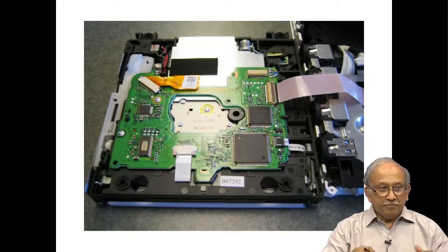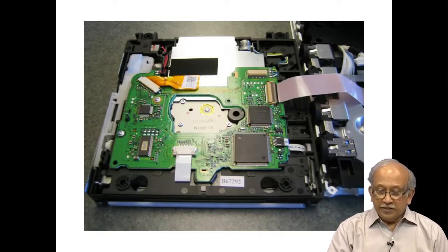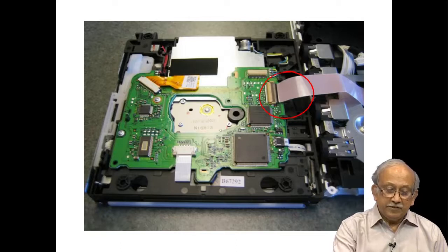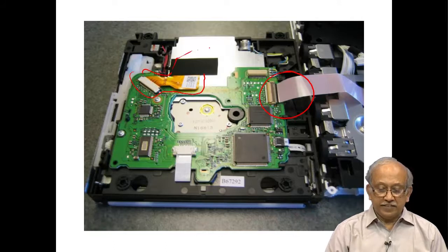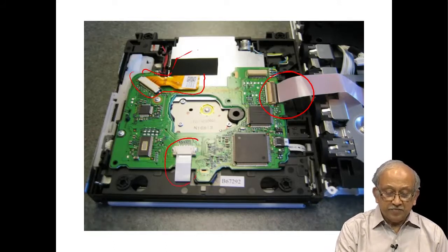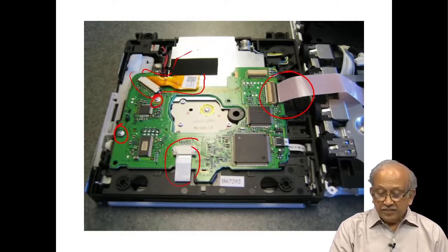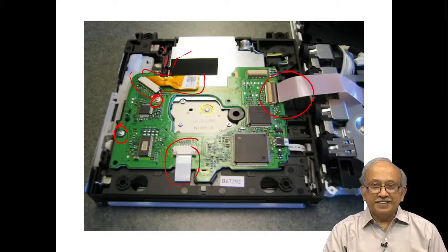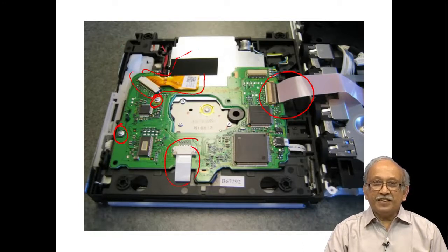That is, you make sure that things fit naturally in all the places. See, in one edge here they have made the connector, and here it is at an angle like this, because the connector is folded and taken off somewhere. And then most important, you have the fastening screws you see here. Two or three things you will notice: fasteners need not be located at the four corners, and very rarely in a professional equipment is the printed wiring board a rectangular thing.